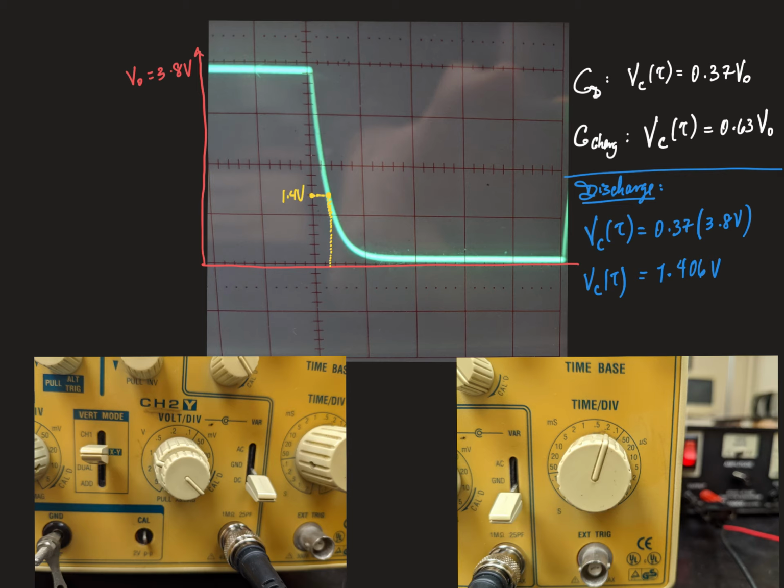I see that I have almost the same result as the last measurement in the resistor, because now each horizontal division is still 0.2. That means that the whole square is 0.2. But this is divided in 5 sections, so this is 1/5, 2/5, 3/5, 4/5, 5/5, which is just 1. So this is approximately 1.5 of 5 divisions.